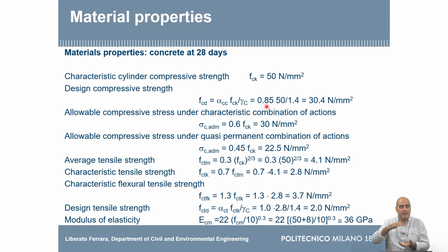Because what happens is that you compact the structure, you compact the pores, and then you form the cracks. And at a certain point, these cracks isolate some micro columns inside the concrete. And if these micro columns become too slender, they break, they fail. So this 0.85 number is to account for this long-term failure effect. So we call it the long-term strength.